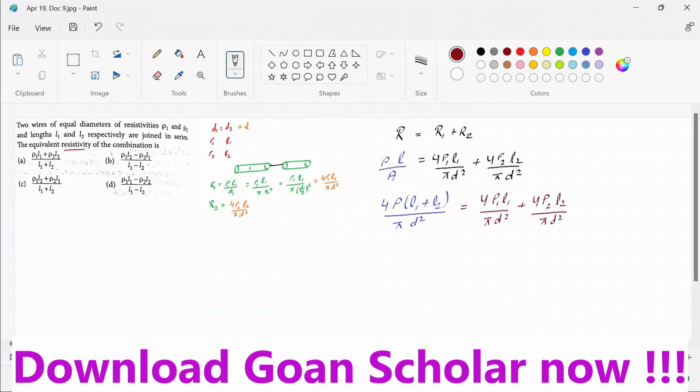Yes, if you are not clear with this thing, speak up. Let's divide the whole equation by pi d square and 4, and let's see what we are left with. Rho, what is this rho? This is the equivalent resistivity, that will be into total length L1 plus L2, and that will be rho 1 L1 plus rho 2 L2. Everything else cancelled. So the equivalent resistivity of two wires having length L1 and L2 connected in series will be this. Is there any option? Yes, option A.